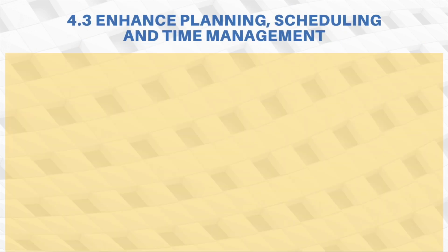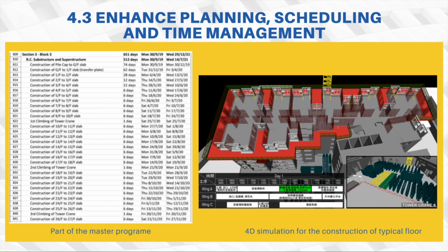Since the master program only reflects the logical sequence and the duration but without the detailed construction activities, with the help of 4D simulation, the time to perform the works, construction activities, and the cycling arrangement are clearly shown. Therefore, BIM supports the visualization of schedule that can identify the potential issue like the time clash on scheduling.